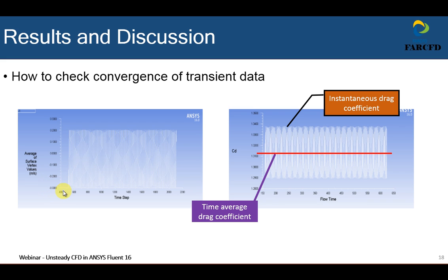The second graph shows the instantaneous drag coefficient plot on the cylinder, which also shows the unsteady behavior as expected due to periodic separation of flow on the upper and lower surface of the cylinder. From this graph, the drag coefficient is approximately 3.13, as we will show in the next slides and also in part 2 of the workshop. For accurate calculation of the mean drag coefficient, we will use Microsoft Excel and import the instantaneous drag coefficient file and use some built-in functions to get the average drag coefficient.